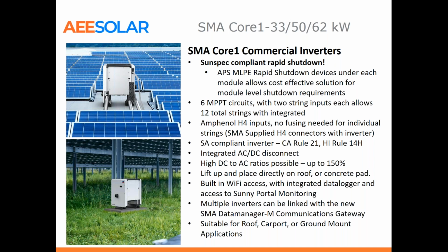What's very nice about these inverters is they're kind of all in one unit. So there are 6 individual MPPT circuits, and each circuit has 2 string inputs. So you can have varying string lengths on each of those MPPT circuits. So you can get a total of 12 strings into each of these inverters. And no fusing is required, since NEC code doesn't require fusing on 2 or 1 DC strings coming into an MPPT circuit.